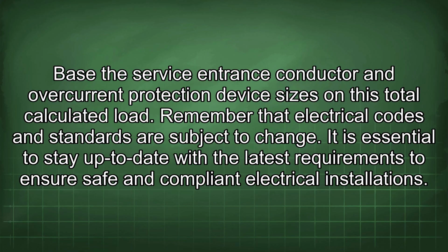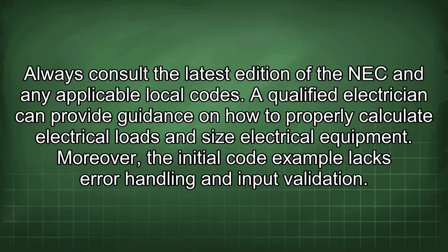Base the service entrance conductor and overcurrent protection device sizes on this total calculated load. Remember that electrical codes and standards are subject to change. It is essential to stay up to date with the latest requirements to ensure safe and compliant electrical installations. Always consult the latest edition of the NEC and any applicable local codes. A qualified electrician can provide guidance on how to properly calculate electrical loads and size electrical equipment.